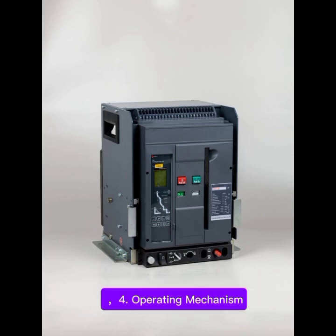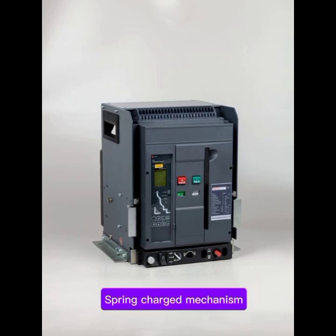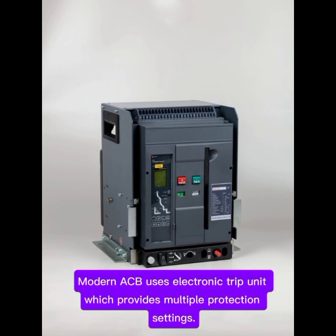4. Operating mechanism. This is the mechanical system that opens or closes the breaker. It can be spring-charged mechanism, motor charging mechanism. 5. Trip unit, protection relay. This is the brain of the ACB. Modern ACB uses electronic trip unit, which provides multiple protection settings.